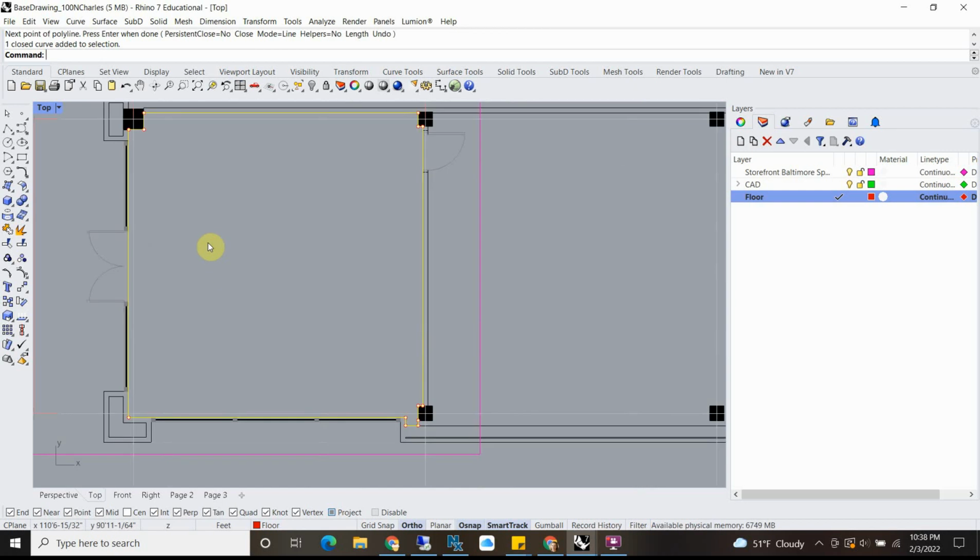If I wanted to build this originally and make something to a dimension, the process is similar, but you need to type. So for example, let's say I wanted to make a 3x8 table in the middle of this room. I would click, come straight down and type in 3 apostrophe for feet. You'll notice up in the command line at the top that it pops up. Then hit enter and then click. Then come over here, type in 8 apostrophe for feet, hit enter, click. Then back up, 3 apostrophe, enter, click. And for the last one, I'm just going to align to there.